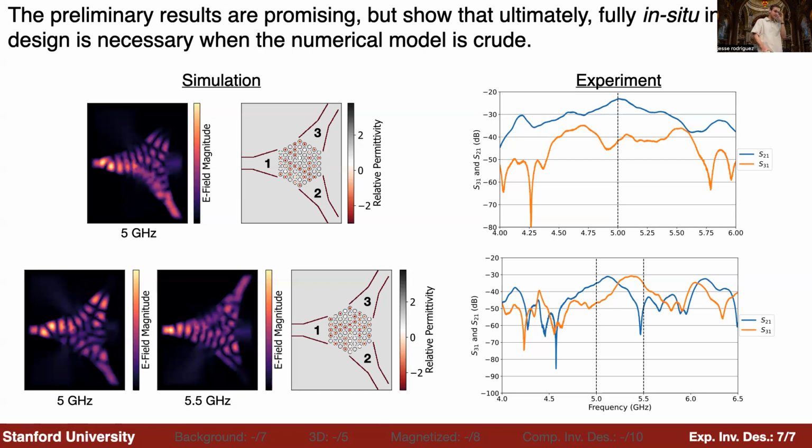So the beautiful thing about using plasma elements is that we can do this entire inverse design process in situ. You can forget the simulations. You just perturb the plasma element densities, take the transmission spectrum out, and come up with some sort of performance metric. You want really big isolation at one frequency and another, and you can let it iteratively train itself how to do these functions. You just come up with a function you want to do.